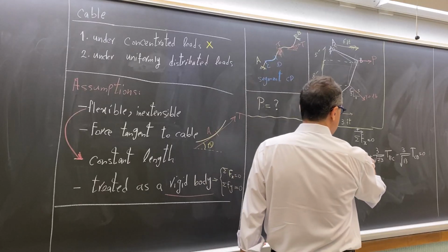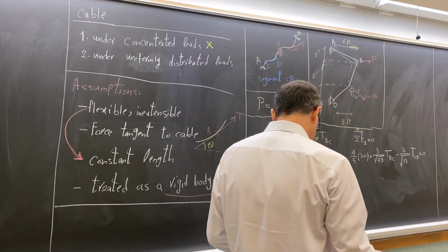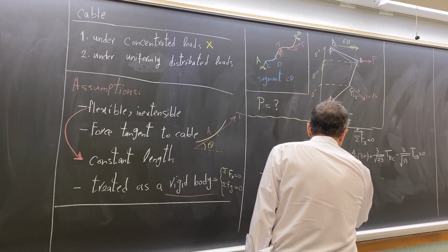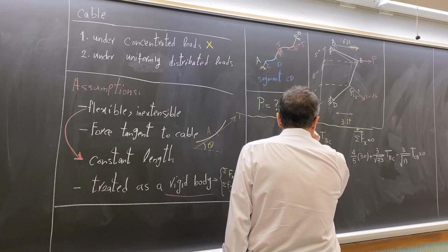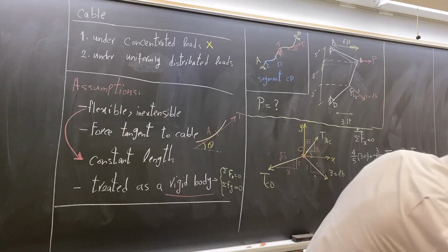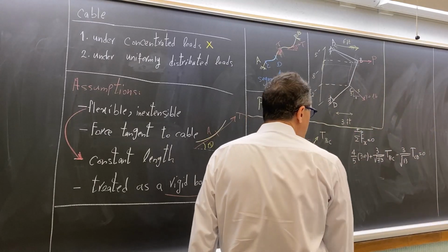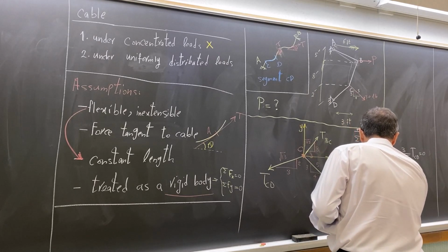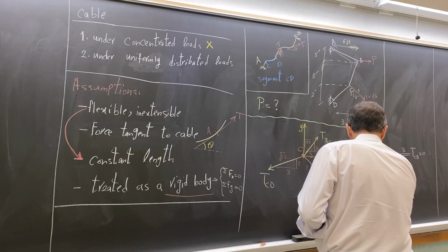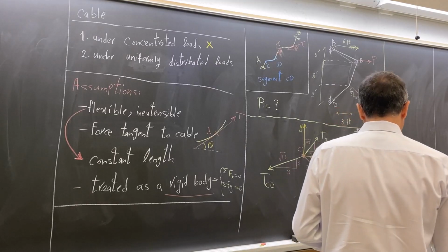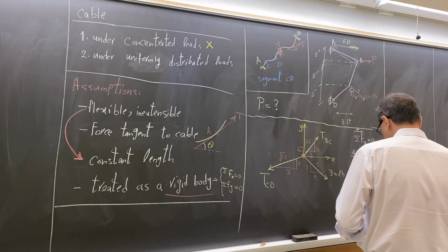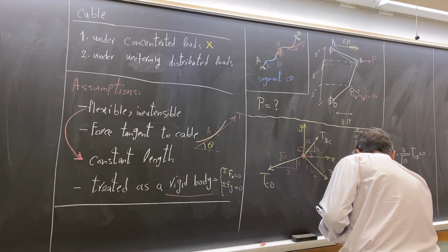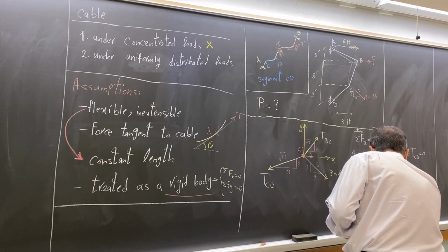These are just the components of the forces along X and Y. So basically the coordinate system is like this. This is X and this is Y. And then we just find the components of these forces. And then we write sigma Fy equal to 0. The conventional sign is assumed to be upward. So 8 divided by square root 73 times TBC